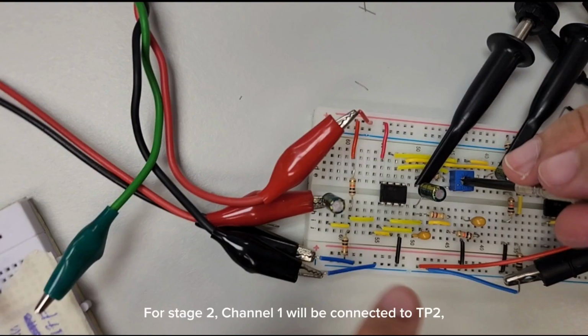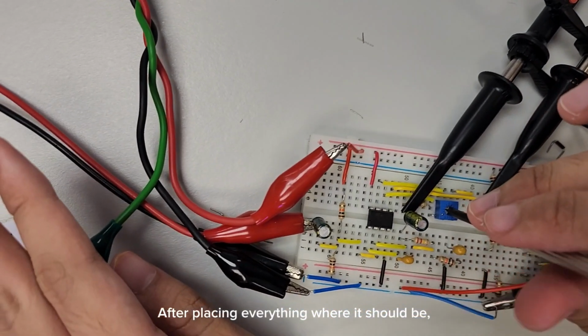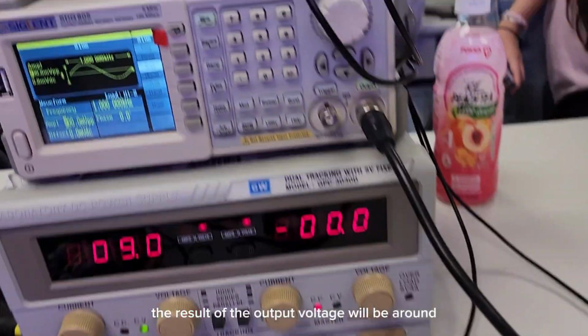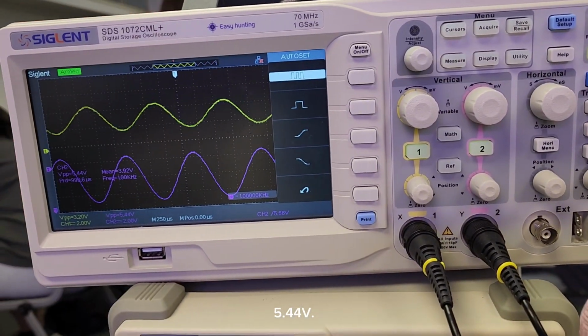For stage 2, channel 1 will be connected to TP2. The frequency and power supply will remain the same, and then connect channel 2 to TP3. After placing everything where it should be, the result of the output voltage will be around 5.44 volts.